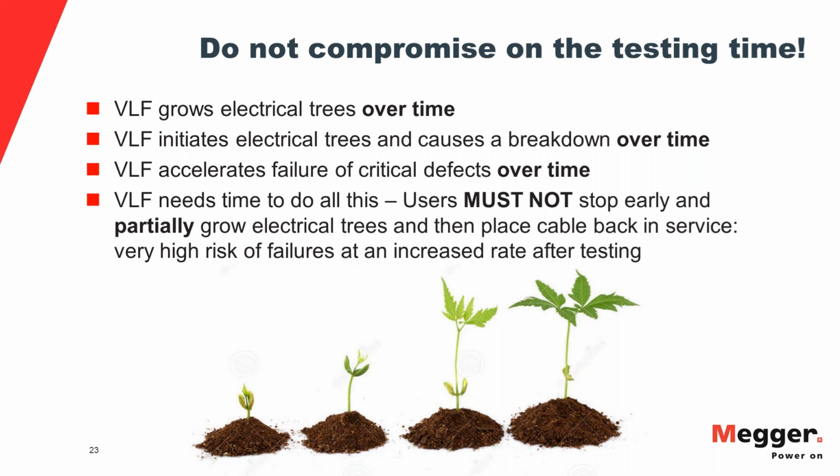And just to point this out, and I'm sometimes guilty of that as well, in the heat of the moment, sometimes you misspeak. The VLF test is doing nothing to the water tree, essentially, more or less nothing. So if the water tree doesn't have a critical length, or the many water trees that you typically have, just to get this misconception out of your heads, when we're talking water trees, it's typically not a single water tree in a certain volume of the cable, a certain section of the cable. It's many, many, many hundred water trees over a bigger volume, and also many, many hundred electrical trees. And which one is the critical one?